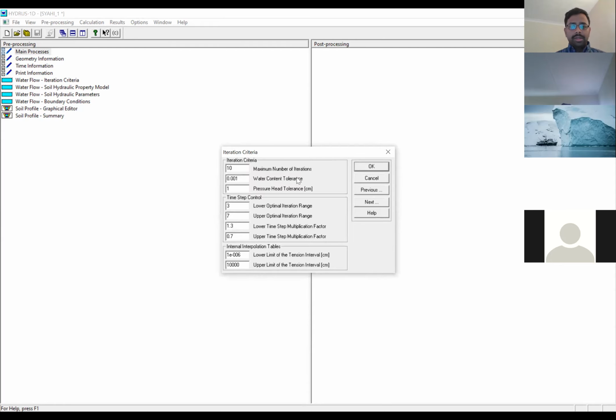Okay. And then they are asking for the number of iterations. So in case of number of iteration, then again we have to take care, we have to try to iterate the numerical domain for like maximum time. In this case, I'm selecting like 50 time iteration, or one can select 100 time iteration, depends on numerical capacity, and it will take little more larger time if you select the largest iteration number. And then we have to minimize this water content tolerance.